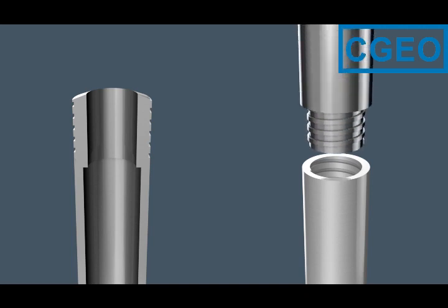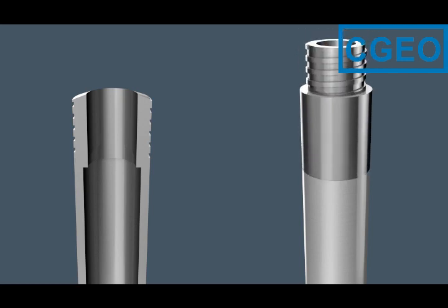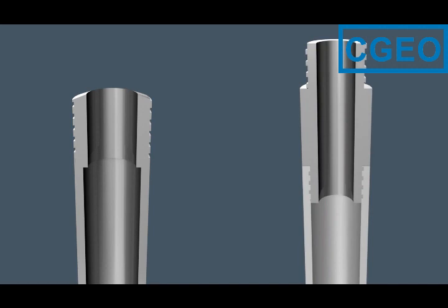The aluminum drill rods are also equipped with steel couplings, but these are threaded and glued to the aluminum body. With only half the weight, this gives the aluminum drill rod almost the same properties as the steel rods, but with higher wear. The dimension of the aluminum drill rods must be adapted to the dimension of the core barrels.